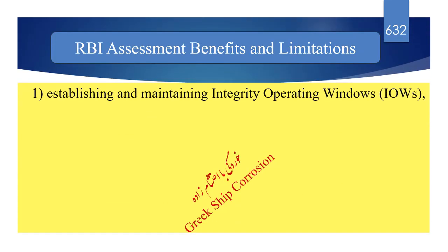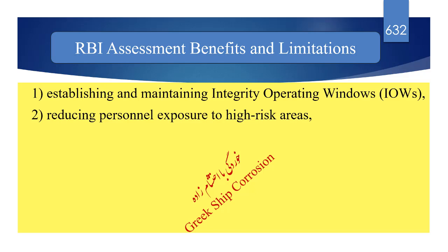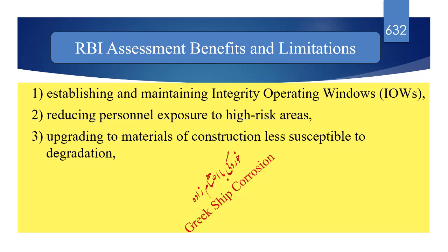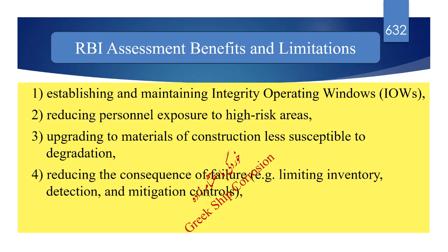1. Establishing and maintaining integrity operating windows, IOWs. 2. Reducing personal exposure to high-risk areas. 3. Upgrading to materials of construction less susceptible to degradation. 4.